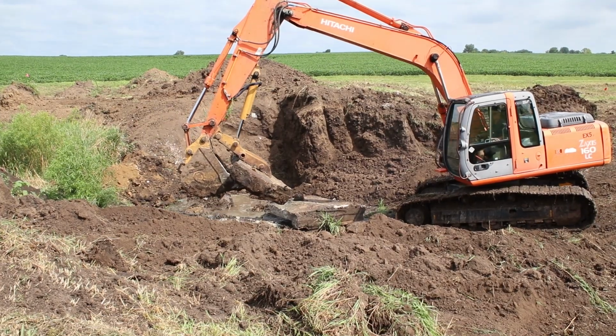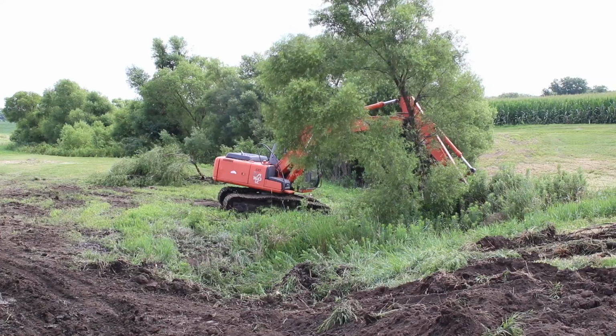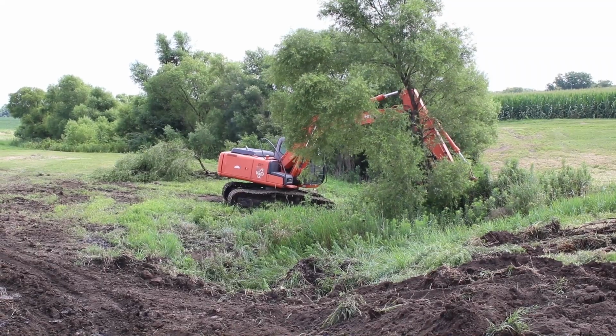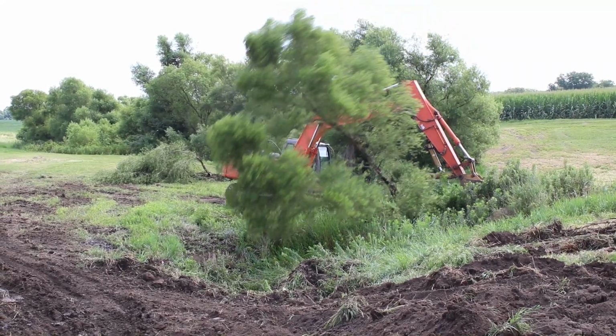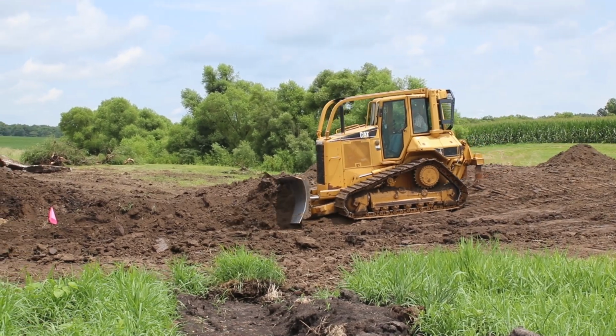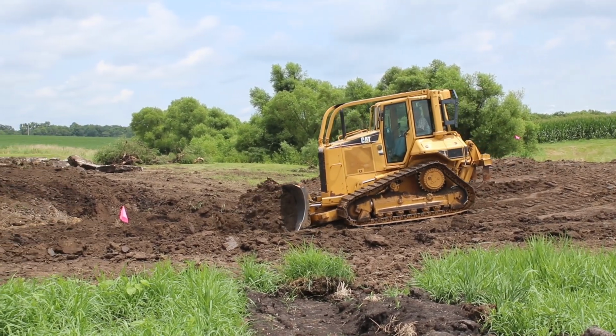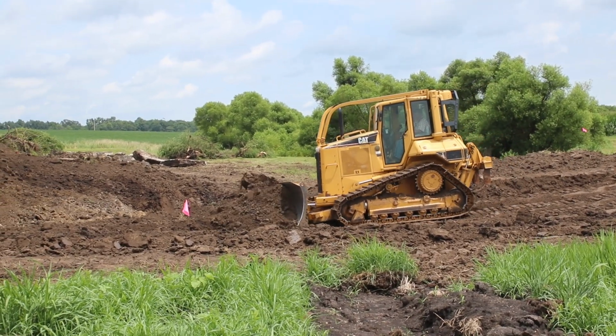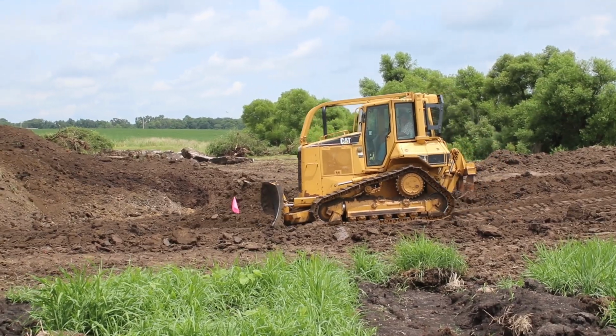The concrete block mat requires a firm subgrade, free of any debris or vegetation, or anything else that would prevent good contact between the mat and the subgrade. With the site cleared, the dozer can begin rough grading. Here he is going across perpendicular to the slope of the chute.